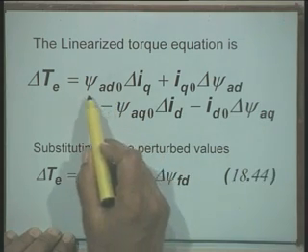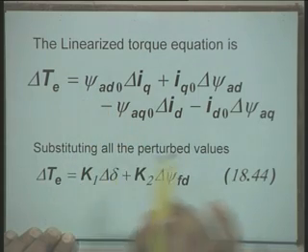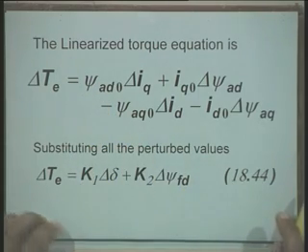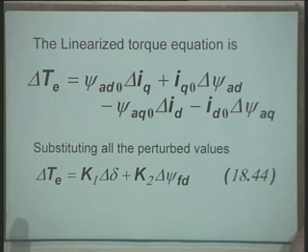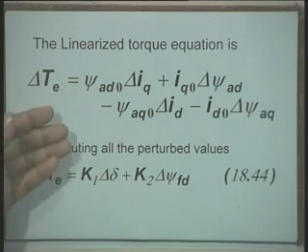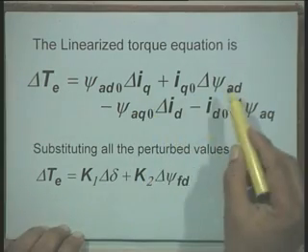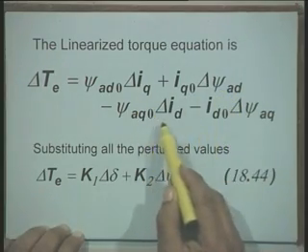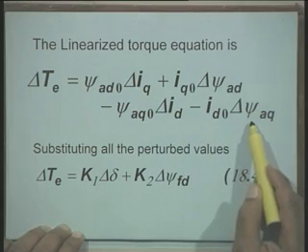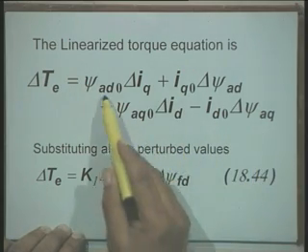Here actually we are considering the saturated values, S is not written just for the simplification. Okay. Now, we have the expressions for delta I D and delta I Q. We have also obtained the expression for incremental changes in the air gap flux linkages psi A D and psi A Q, right. Therefore, when you substitute these incremental quantities, that is delta I Q, delta psi A D, delta I D, delta psi A Q, right, and these are the initial values.